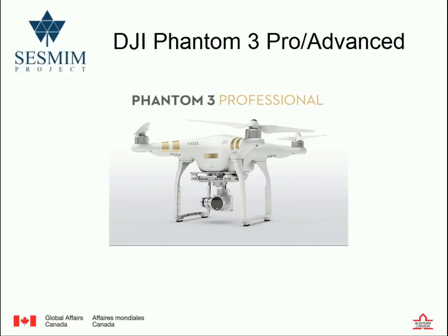The Phantom 4 giving you 20 megapixel images really does not enhance the aerial mapping. It just makes the computation longer for the processing. In terms of our research, the sweet spot for images is around 16 megapixels.